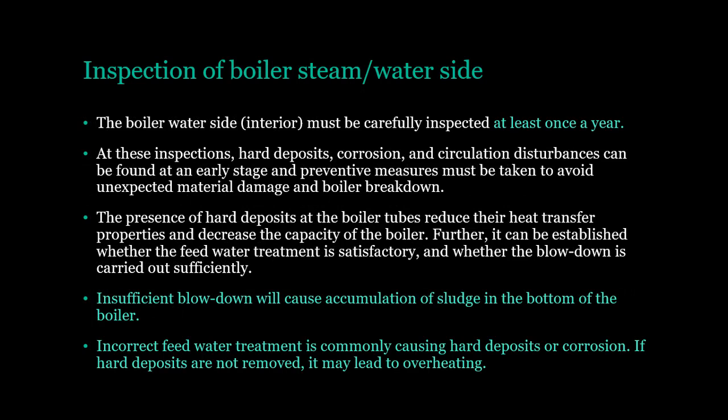Inspection of boiler steam/water side. The boiler water side, interior, must be carefully inspected at least once a year. At these inspections, hard deposits, corrosion, and circulation disturbances can be found at an early stage and preventive measures must be taken to avoid unexpected material damage and boiler breakdown.